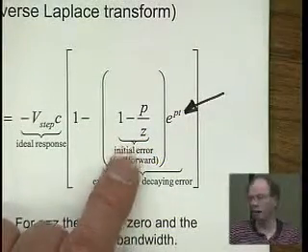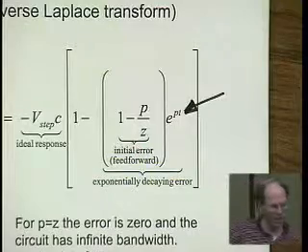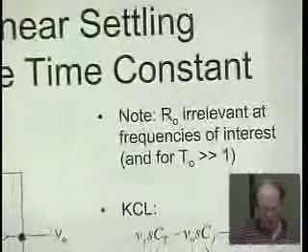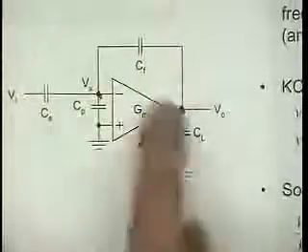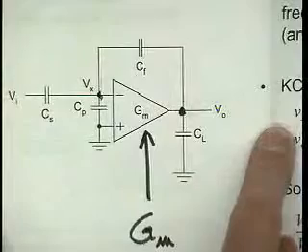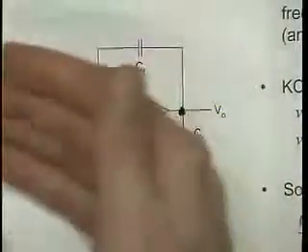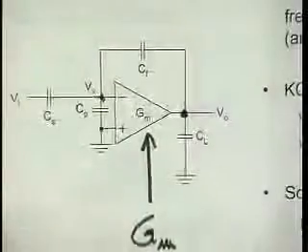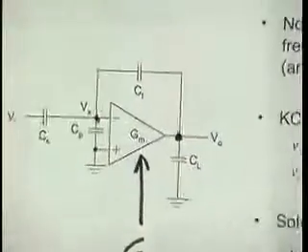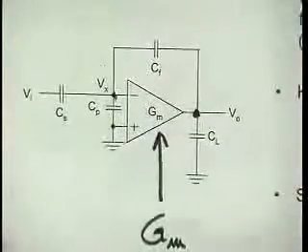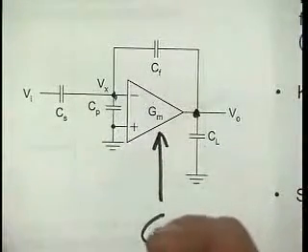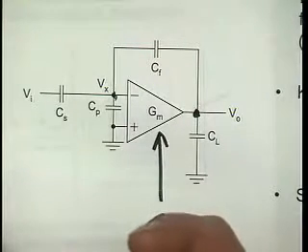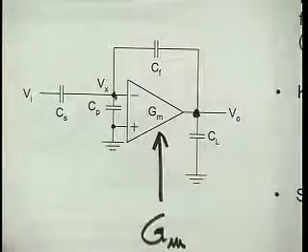And the other thing is, of course, at this point you're really relying on the input driving the output, and so the impedance of this circuit may not be quite ideal. You may want to have a more constant impedance over a broad range of frequencies. That's another thing about an oscilloscope probe. They tell you that the input impedance of the oscilloscope is a megaohm or something, or 10 megaohms. Well, yeah, at sufficiently low frequency, and at higher frequency, of course, not.